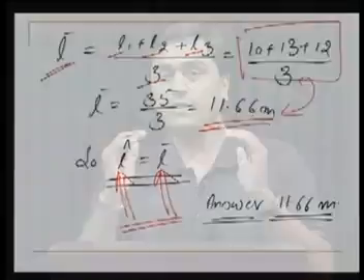So what we have seen in this video lecture is the condition equation method. How do we start from the beginning? We have to look into the problem, where the conditions are. We have to see how many observations have been taken, what minimum number of observations are required in order to define the problem, and find the redundancy. Once the redundancy is known, then we write an equal number of conditions. So we have to look into the problem, where these conditions are.